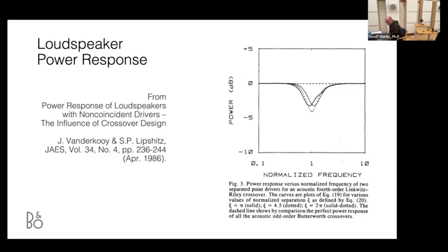The problem is that if you're looking at the power response and you've equalized the on-axis response of the speaker to be flat, then you will have this dip caused by the separation of the two drivers. Those 4 curves that are shown there are for different separations of the drivers, but regardless of how far apart the drivers are, we're just playing with how big that dip is. And like I said, because we're Bang & Olufsen and because we're worried about the power response, we have two choices in this simplistic case.